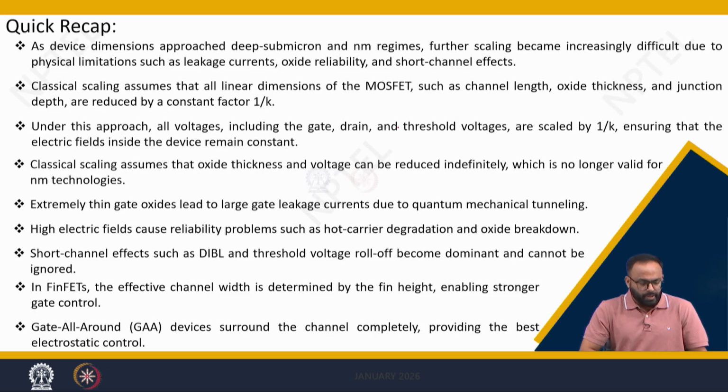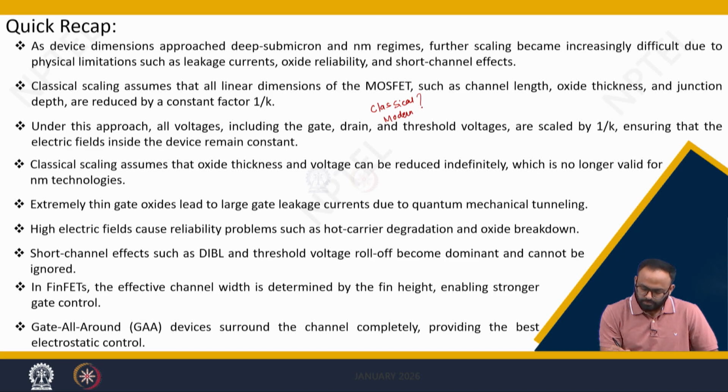So, let us do a quick recap. In the previous lecture, we were discussing the classical and modern scaling techniques. We said that the growth of the semiconductor industry is dependent on scaling, meaning how efficiently you scale the long dimensions of the MOSFET to a short scale. We said that classical scaling follows some set of rules, which we divided into two parts: one is constant voltage scaling and one is constant field scaling.